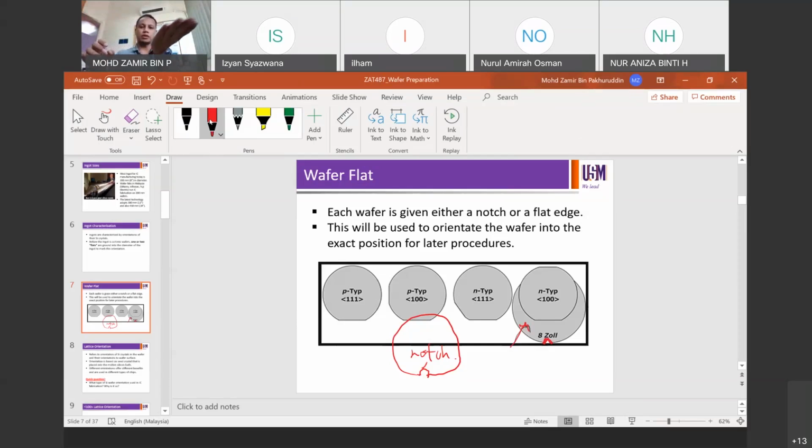Sometimes the wafer coming in by the robot arm is random in nature. It may sit at any angle on the robot arm. Then when the robot arm sends it in and puts it down there, before the process actually starts, the wafer has to be aligned to home position or zero alignment. There we have a sensor, a detector at the bottom, and the notch opens a way for the sensor to work.